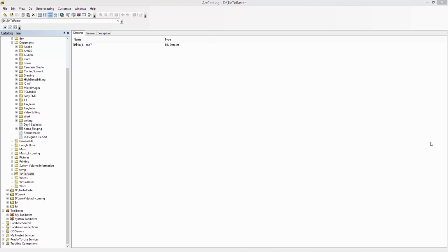So first what we want to do is set up ArcCatalog so that we have the necessary tools available. First up, we're going to disable background geoprocessing. Now, the reason we're doing this is that background geoprocessing works just fine, but it gives you less diagnostic information. When you're running a tool, you'll see a blue progress bar at the bottom of the page, but it can be hard to tell exactly what's going on and what progress the tool is at.